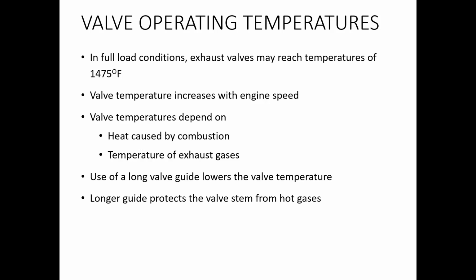And the temperatures may reach very high during the full load conditions of the engine. As high as 1475, it can go almost up to 2000 or 2500 degrees Fahrenheit. Such high temperatures, these valves must withstand. And as engine speed increases, the temperature inside the engine also increases. The valve temperatures depend on the heat caused by combustion and the temperature of the exhaust gases. So both of these are causes of raising the temperatures of the valve.